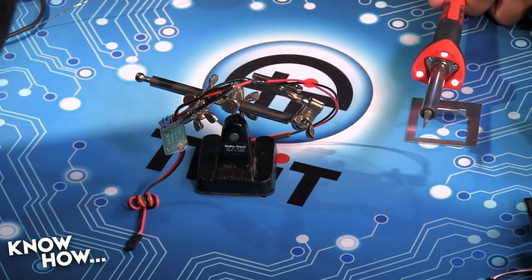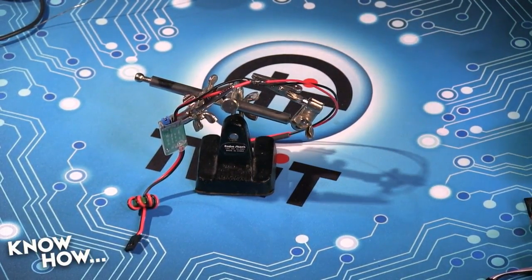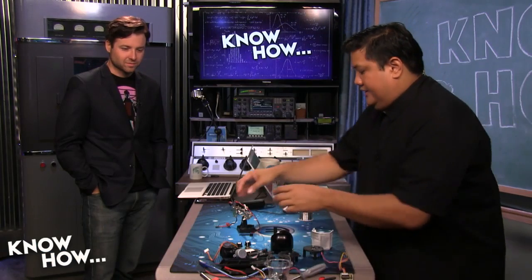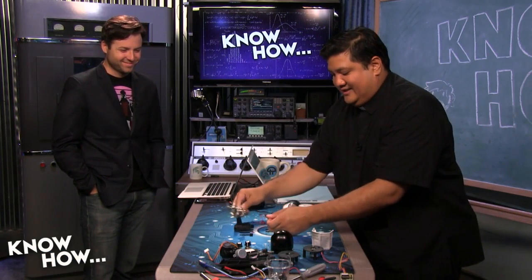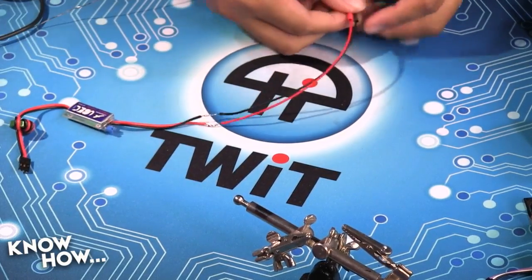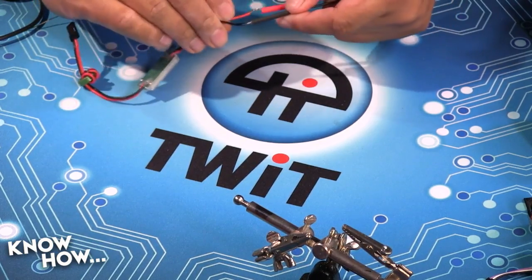All right, looks good. Okay, soldering iron off. Let me put that off to the side so that it just burns air. Put it very near me. So what we've got now is a very simple joint. I'm going to go ahead and run the heat shrink tubing back over that.